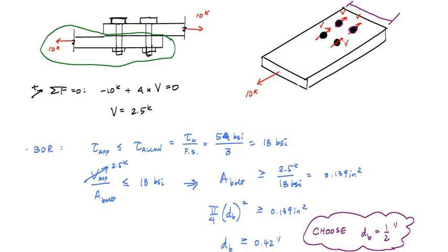That's already 1 inch, and then I have some space requirements here so that I can fit my tools to tighten any bolts and nuts, and so that there aren't any other failure modes that can occur. But that's more if you're designing steel structures or other metal structures, and there are minimum edge distances and spacing requirements.